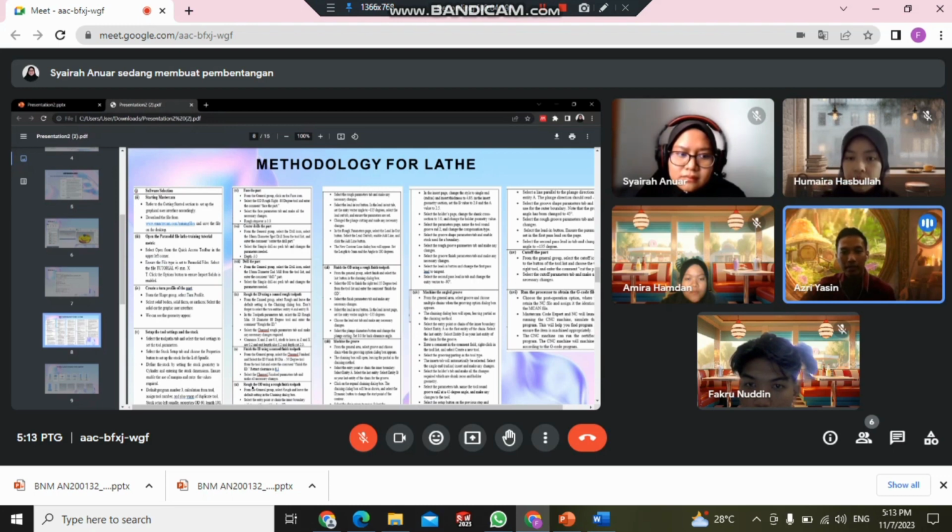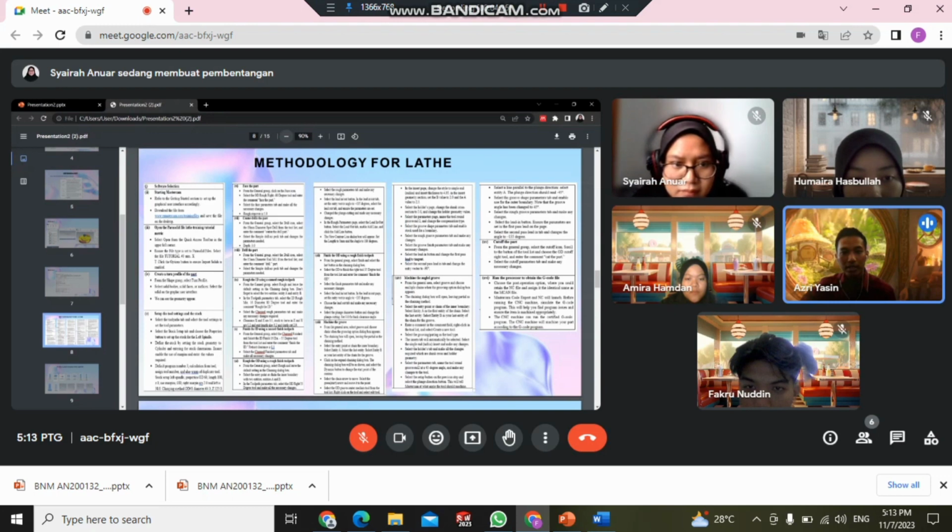Okay, from the chain group, select rough and select the two entities, which are entity A and entity B. In the toolpath parameter tab, we choose the ID rough 16 diameter 80 degree. Select the chain finish and select the ID finish 16 diameter negative 55 degree tool and retract clearance is 0.1. Select the entry point or chain the inner boundary with the two entities A and B. Select the OD right 55 degree, in lead in/out change the right angle and also length.